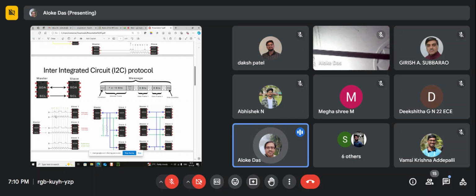If this clock signal becomes slower, meaning bigger, then the same waveform will be decoded differently, because the edge is coming differently. Whenever the edge comes, only at that time it will be sampled. So if the edge comes at a different time, or less frequently or more frequently, the same waveform of the SDA line can be decoded differently.